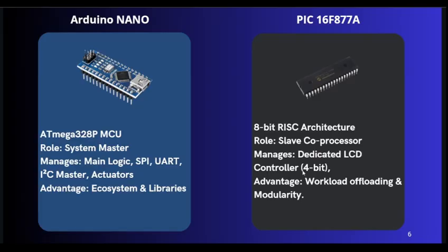For the visualization task, we selected the PIC16F877A. In our design, this powerful microcontroller acts as a slave coprocessor. Its sole and exclusive function is to receive commands via I2C and manage the LCD 4-bit interface.